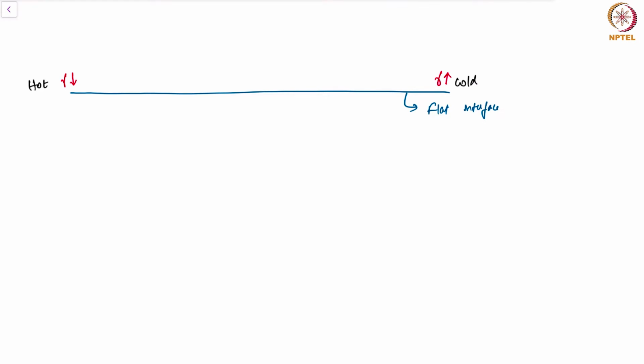The reason this happens is, for most fluids, you can assume that surface tension is given by this relation: gamma is gamma naught times (1 minus delta (T minus T naught)). So this relationship allows us to understand how surface tension varies with temperature. You can clearly see that when the temperature is equal to T naught, the surface tension is gamma naught, and this quantity delta is like a sensitivity parameter. It tells us how sensitive the surface tension at an interface is to temperature variations.